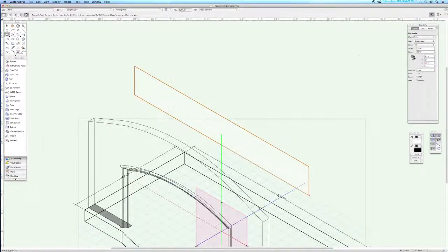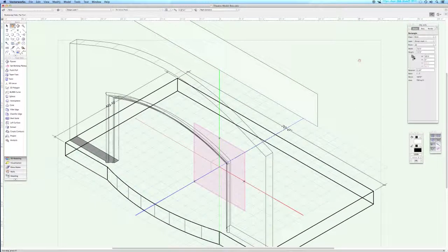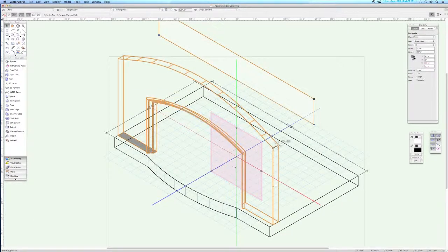I'm going to go back to my right ISO. I want to extrude it the same dimension as this, so I need to find out what that dimension is. There's a ruler. It's probably under dimension and notes. Tape measure, there it is. And the tape measure is the / key. I'll use that a lot.